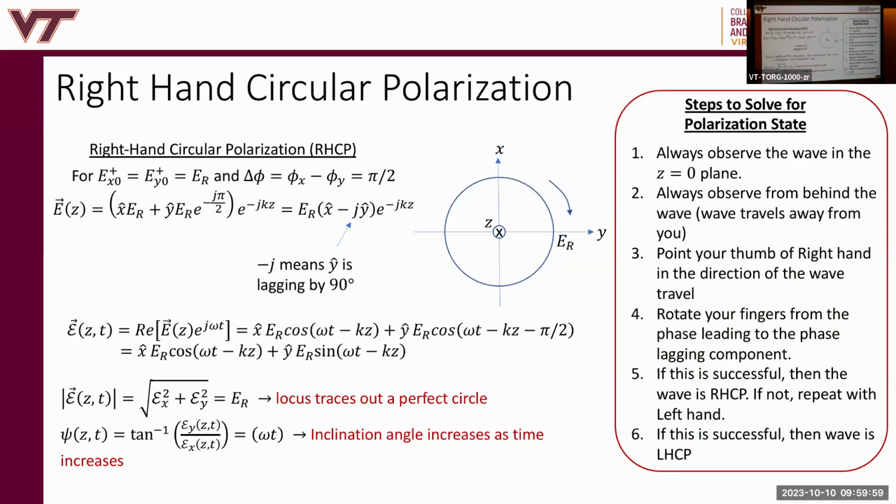Is it practical to modulate the X and Y components so we can encode information into the polarization? Yeah, definitely. In communication systems, you can design a system that encodes information on different polarizations in order to pack more information into the channel. So we can do orthogonal modulation schemes where the functions are orthogonal. So we have some weird trace in the XY plane.